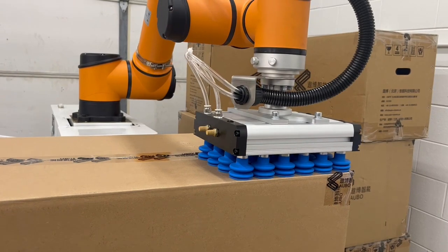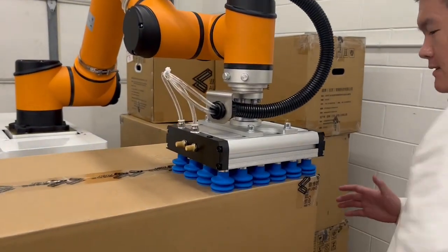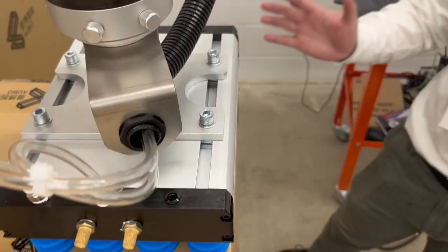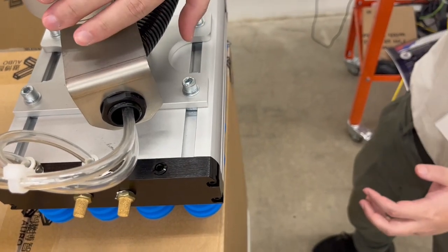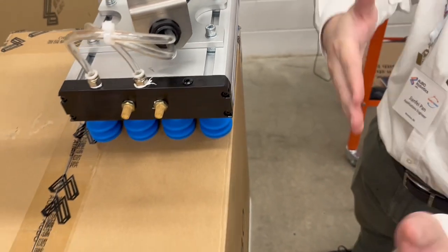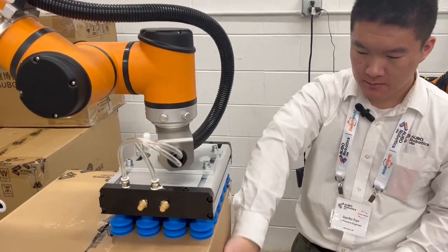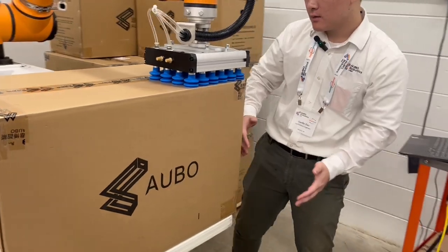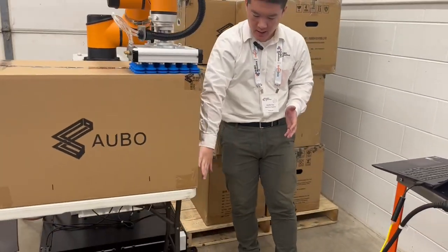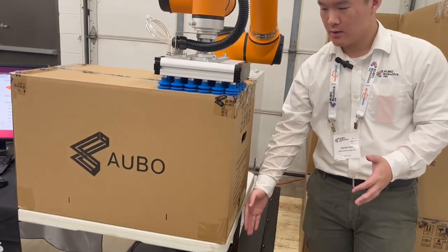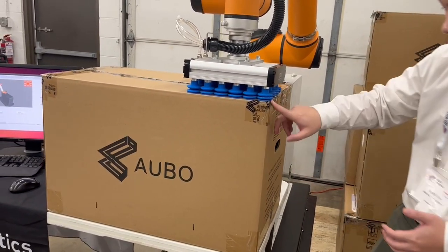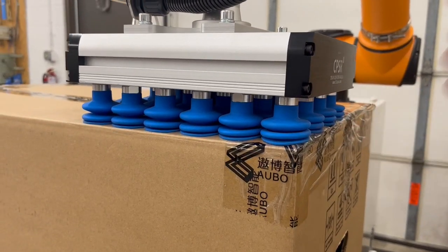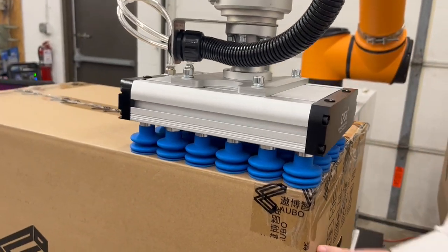Okay. So this will be the point that I'm going to save, which determines this configuration here. This connector is pointing at the incoming products, and this surface is on the inner edge of the conveyor. And this side is on the other side of the stopper here. So they'll be flush, and there will be a certain compression of the suction cup, such that if the vacuum is activated, it could pick this up.